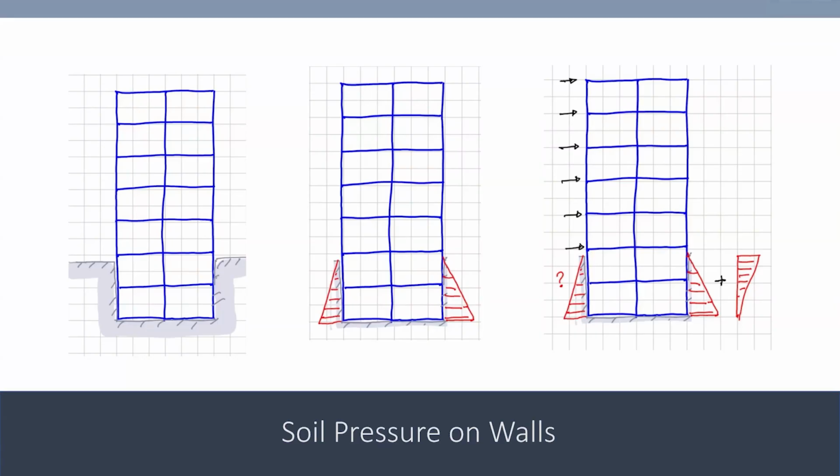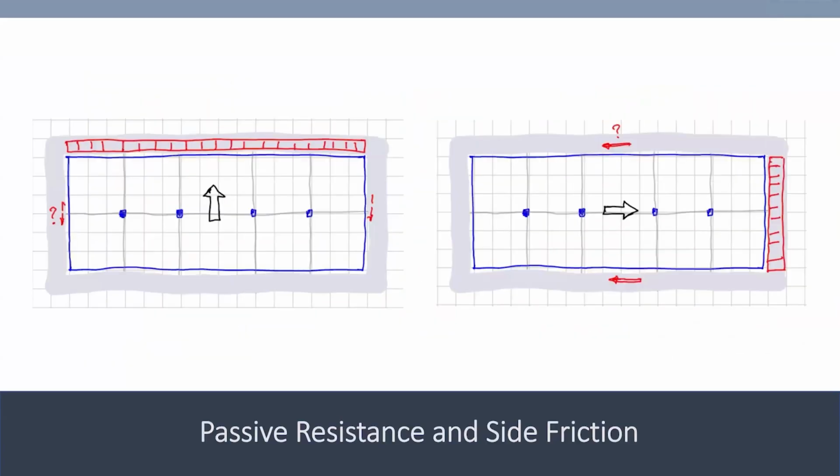Once again, we need to find how much the extra pressure is, and this is given by ASCE. There's a formula to calculate that. They have estimated how much you will get depending on the soil type and all of that. So you can estimate the extra soil pressure like that. But this is not the end of the story.